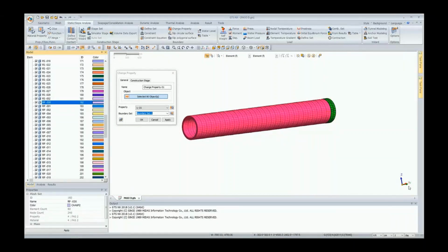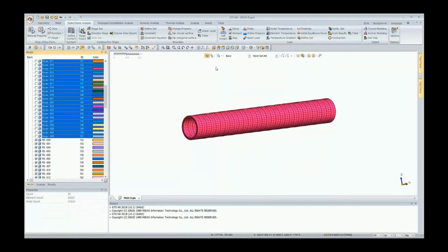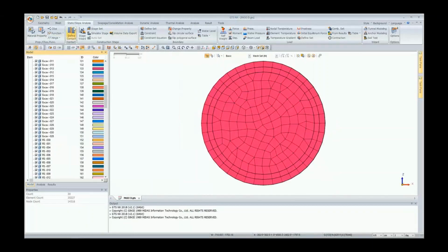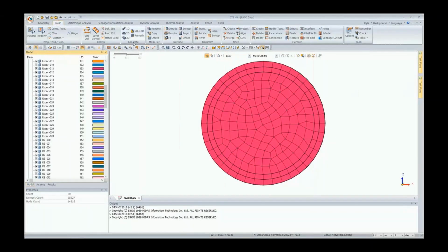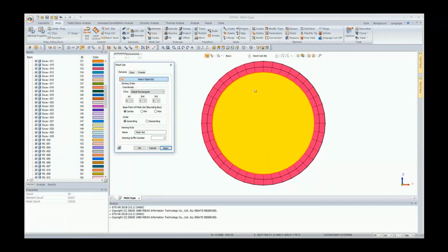And we want to do this for the primary and secondary supports. What we also need to do is organize the order of our supports. And for that, we should do this first before changing the properties so it's organized. So what we want to do is use this command called meshset rename. What this allows me to do is, for instance, select my sets.